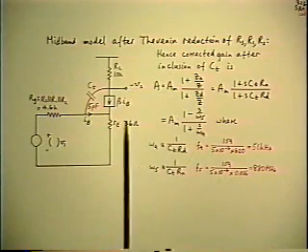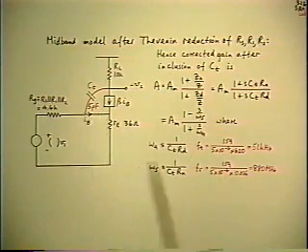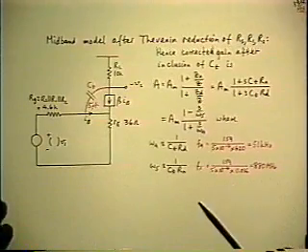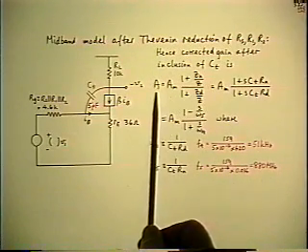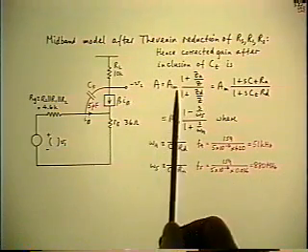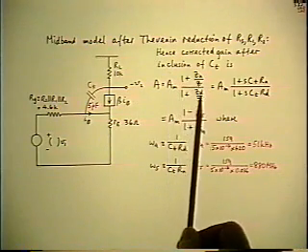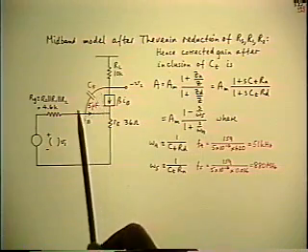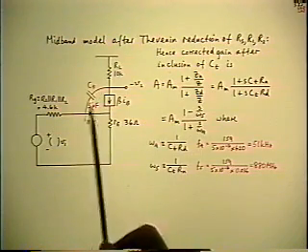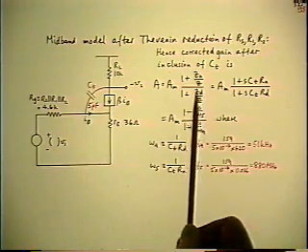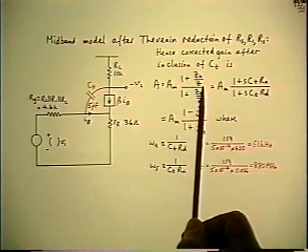Okay, let's assemble the result. We now put the CT in. That's the extra element. And the result is the gain in the presence of the CT is the reference gain AM that we started with, multiplied by the correction factor for an extra element in parallel. So it's the first version of the theorem, 1 plus Zn over Z in the numerator.